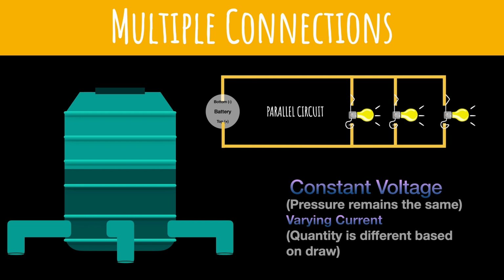So does that mean a parallel circuit is better, that we need just a smaller power source to power multiple items? No, that is not true. The multiple LEDs drain the power from the battery much faster than in the series circuit. So there is still conservation of energy. Another small difference between a series and parallel circuit is that in a series circuit, you just need one wire running through all the LEDs, whereas in a parallel circuit, you need two wires connecting to each of the LEDs. So what that means is you need to have more connections.